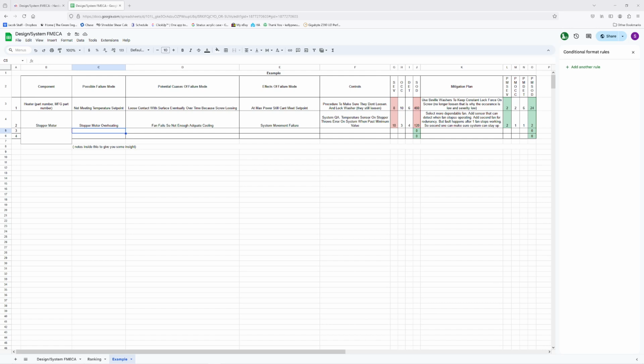Same as the safety FMECA, you want to keep these updated. So when something happens, add it here. Let's say you have a failure that you didn't come up with. For example, on the Micronics, it was their powder getting jammed in the auger. So you put that on here: what are the possible failure modes, and what's your mitigation? Make sure this document keeps up to date. This is not a one-time thing where you spend 3 hours and you're done. You're doing this continuously throughout your development process, or you can have one person dedicated to do this the entire time for all your products.